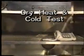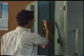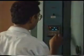Dry heat and cold test. Dry heat and cold test is conducted to determine the suitability of an equipment for use at high or low temperatures. The equipment is placed in a chamber which is capable of maintaining the temperatures from 40 degrees Celsius to 200 degrees Celsius with a tolerance of plus minus 2 degrees for dry heat test and up to minus 65 degrees Celsius for cold test.